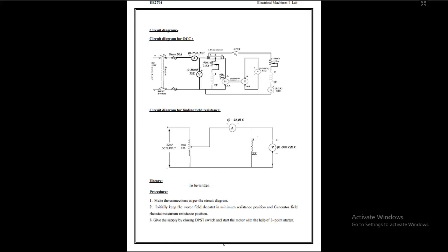And in order to operate the motor, an electrical supply is required. So I am giving the DC supply here. This is the DC supply. In order to operate the switch, a DPST switch is connected, and in order to avoid short circuit and overcurrents, two fuses are connected across this. In order to understand how much voltage is entering into this motor, I am connecting the voltmeter here.